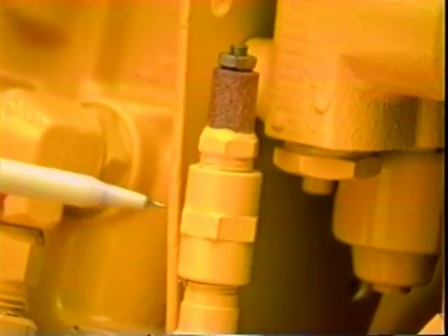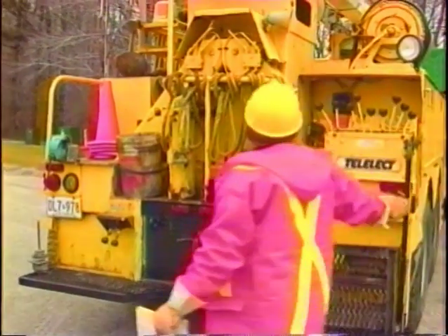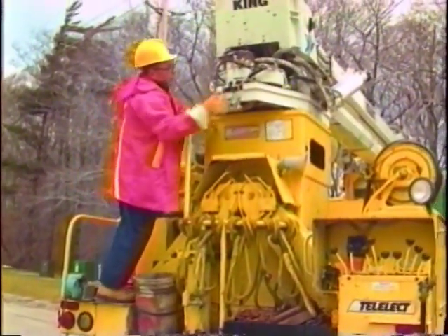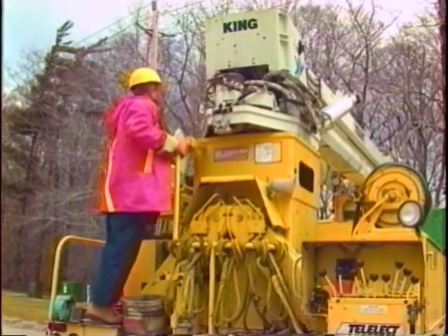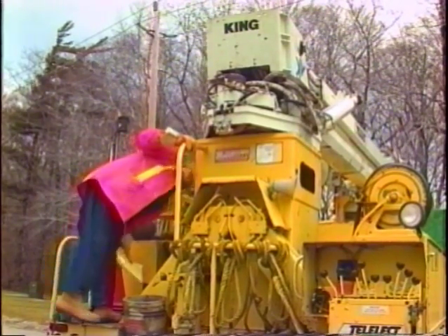To prevent this from happening, the upper boom is equipped with one or more anti-vacuum relief valves. If the pressure in a hose drops below atmospheric, its valve opens, allowing air into the line. The breather filter at the end of the valve must be changed at regularly scheduled intervals. In most utilities, as an operator, you will not be called upon to maintain the systems we have just been discussing, but you are responsible for making sure they are working properly. And that is what we will talk about in the next two sections.